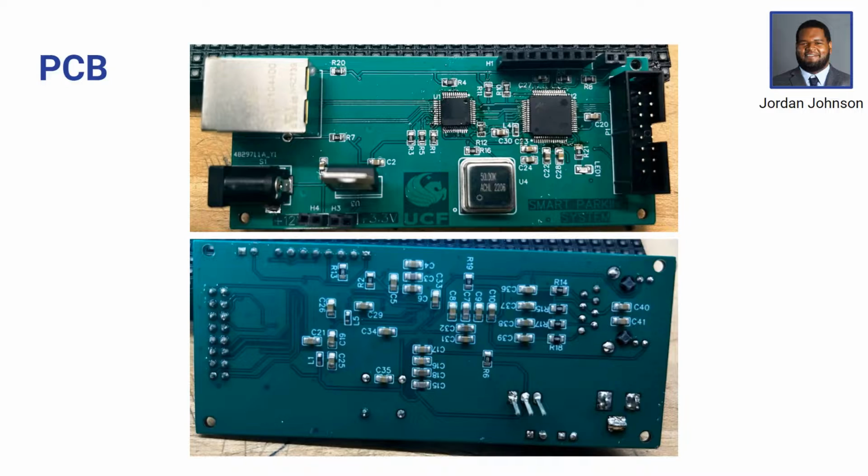These test points could also supply power to the board via an external source if need be. On the right side of the board, we have the PHY chip, which is the smaller of the two chips, our MCU, an oscillator, an 8-pin female header used to connect to the debugger, and a 16-pin male header, which is used to communicate with the LED sign.